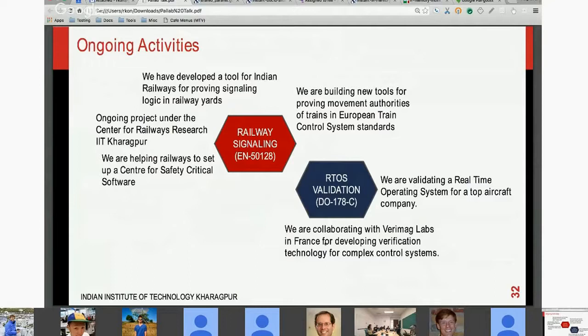For example, in India, we have very old tracks, right? Tracks running since almost the British era. Now, it's very difficult to figure out which track is developing a problem at which point of time, and you cannot afford to go and inspect millions of kilometers of tracks every now and then. So there is an ongoing initiative to see whether we can have sensors which can sense vibrations on the axles of the train. Now, if all these sensors are reporting vibrations at a specific location of the track across multiple trains, then you know that something must be happening there, right?